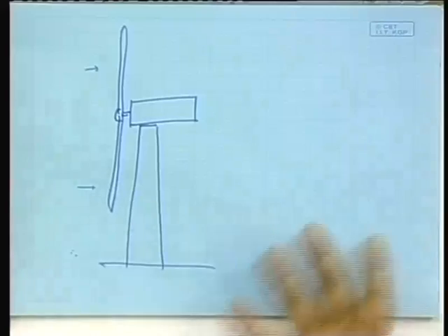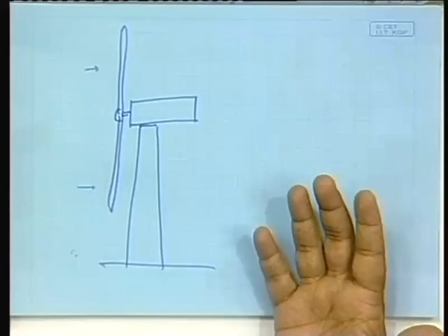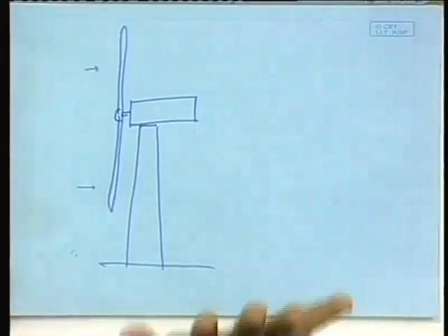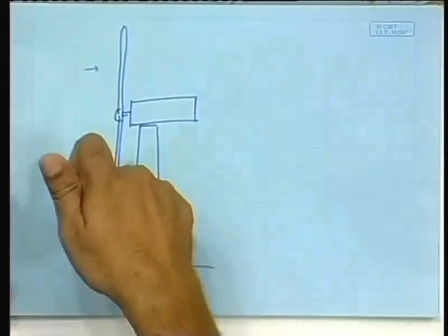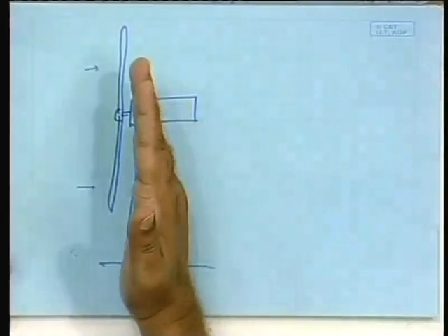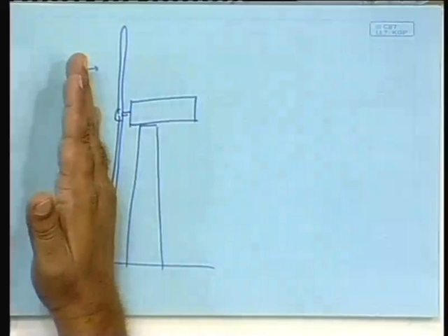If the wind is coming from this side, you can easily see that it will be the tower shadow, right. So, in terms of wind, not in terms of light, wind will be obstructed by the tower, which will not reach the blade that is down there. So, as the blade passes by, when it comes here, it will suddenly run into some disturbed wind, and that happens both for downwind and upwind, because if it is upwind, then also there is a disturbed wind this side.